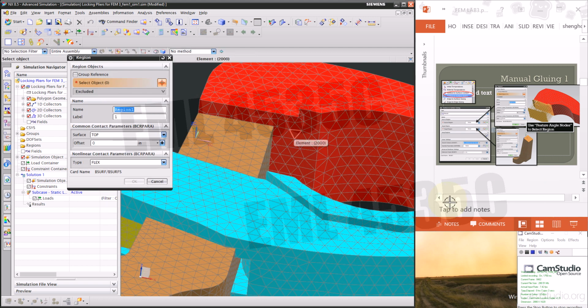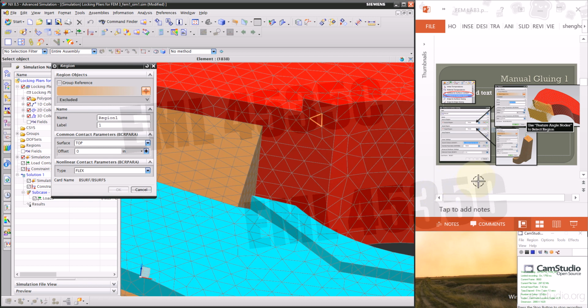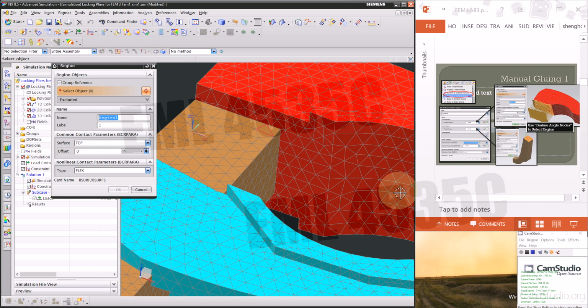We're going to glue this surface to the surface on the handle portion. You can't really pick the face by clicking here, because it's an element. I want to pick all the nodes on this face, so we need to use a method called feature angle element face.